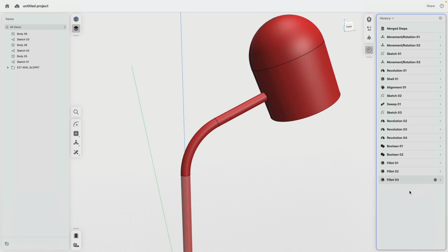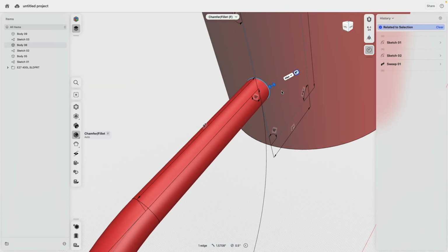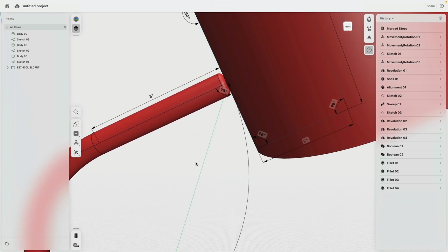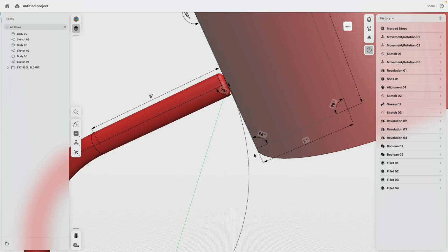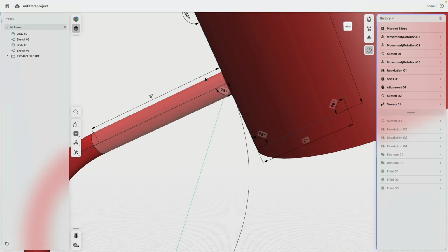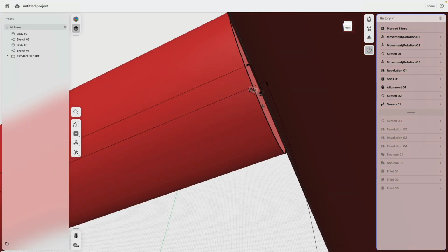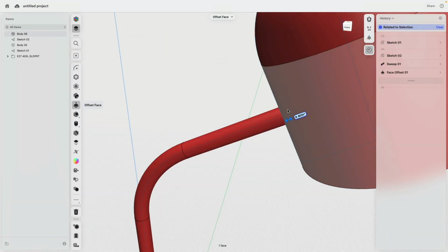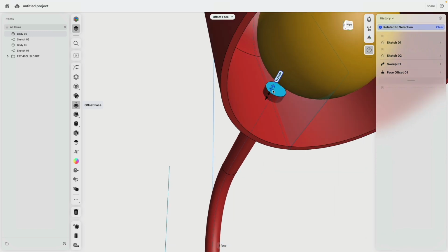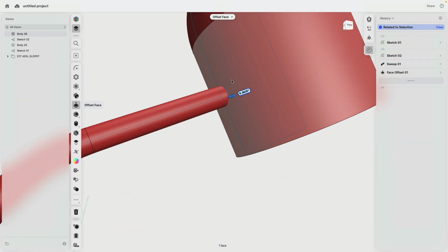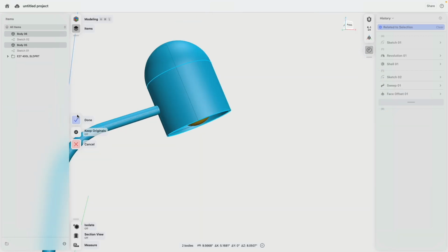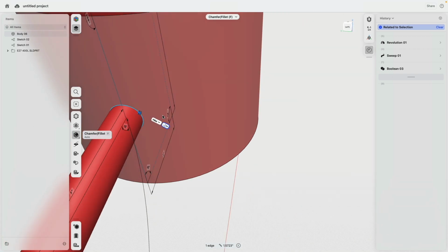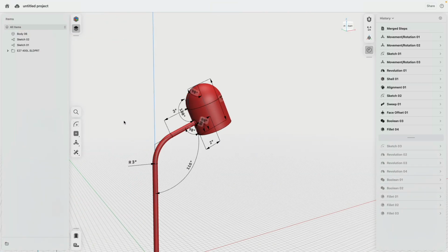Very good. And then at the end of the timeline here, we're going to, what? Oh, I think I have an idea why this doesn't work. Undo. Let's go back to here. Why did this not join? Well, it doesn't intersect. I forgot that. So this face, we bring inwards a little bit, make sure it does not go completely through. So it's inside, and then these join. I think I did this before, but I didn't see that the command didn't really work out. There we are.